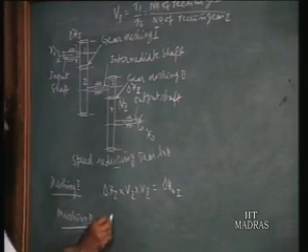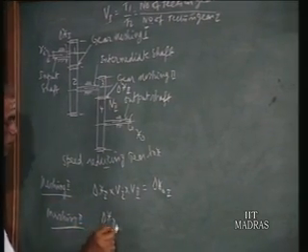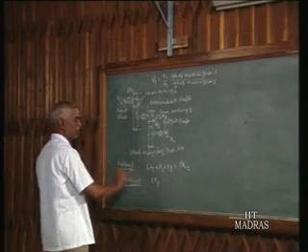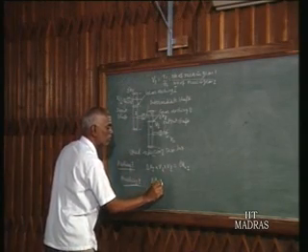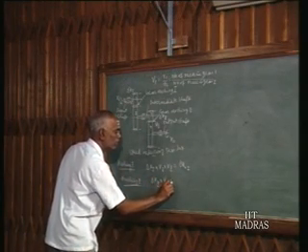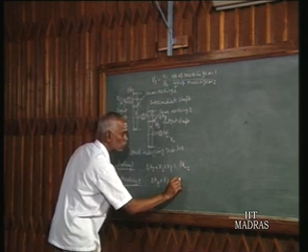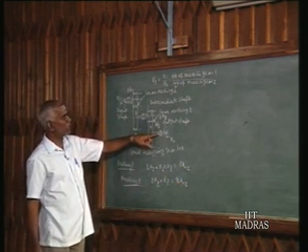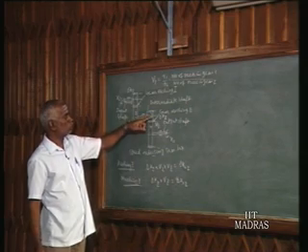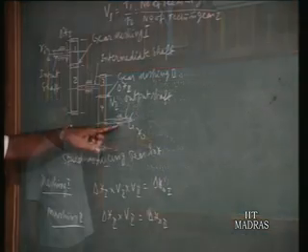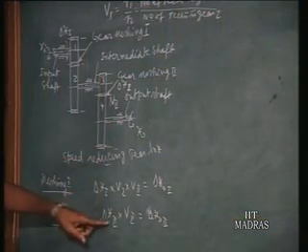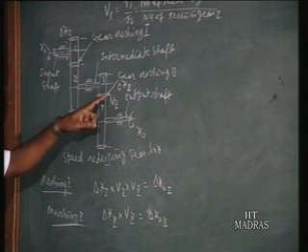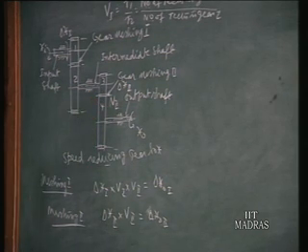So that much motion of delta x2 at the intermediate shaft, into V2, will be the delta xo2. That is the output at the output shaft, delta xo2, will have an equivalent rotation of delta x2 into V2. V2 is the velocity ratio of gear meshing 2.